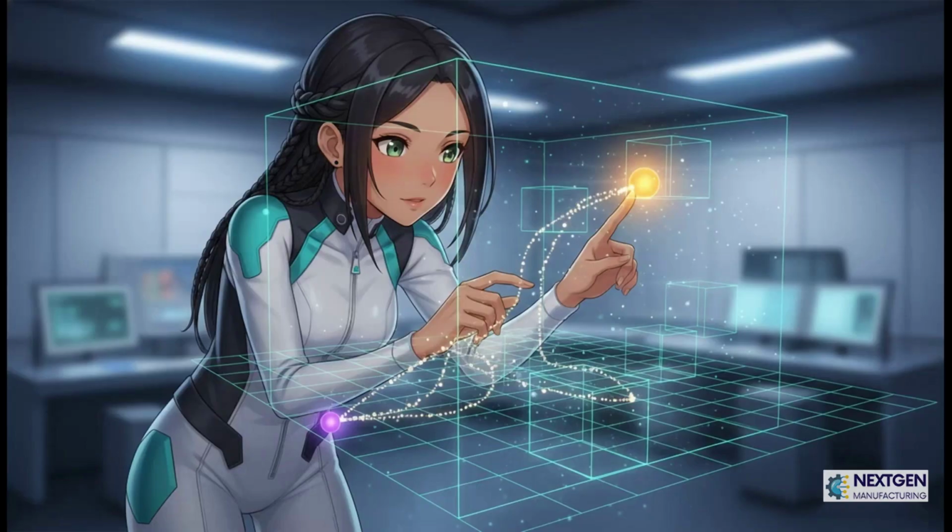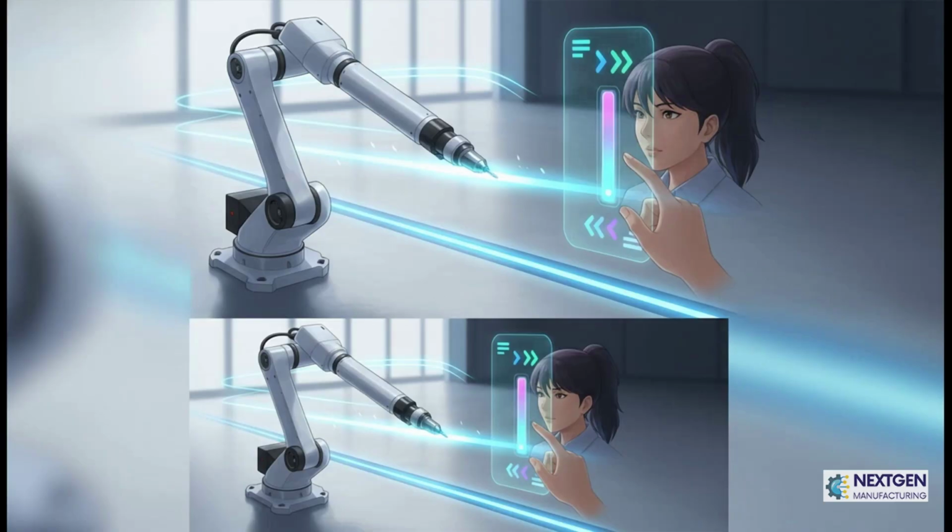Next up, you've got your X, Y, and Z values. And this is super straightforward. It's just a destination. It's like telling your car's GPS, I need to go to these exact coordinates on the map. The machine knows where it is, and this tells it exactly where it needs to go next in 3D space. And that last piece of the puzzle, the F value, that's all about speed. F stands for feed rate, which is just the fancy way of saying how fast the machine should move while it's making that straight line trip to the coordinates we just gave it.